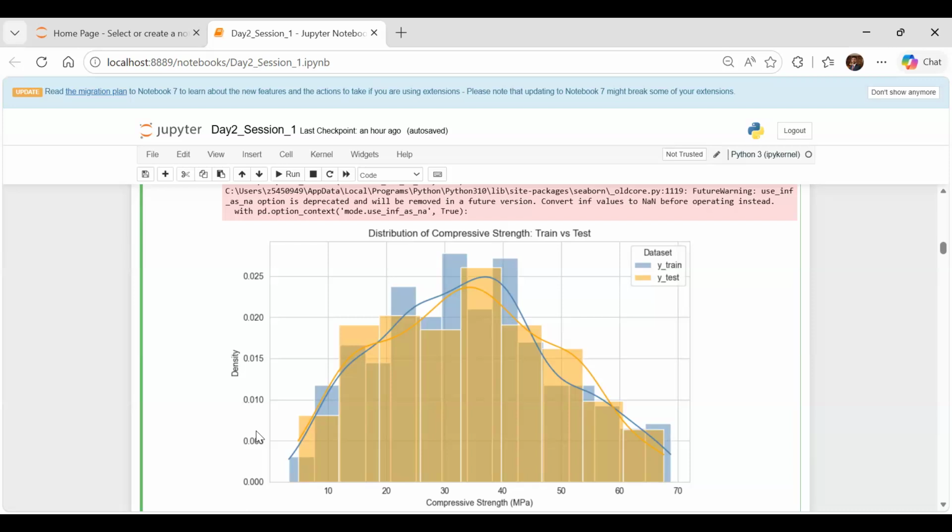In that case, we need to transform those data to different distributions. Say I have the compressive strength data, I take their log value, log compressive strength, so I change their distribution, so that the obtained distribution is now somewhat fittable.